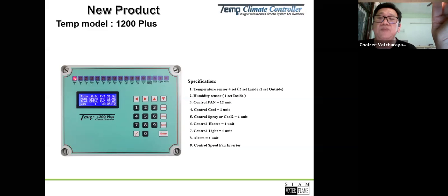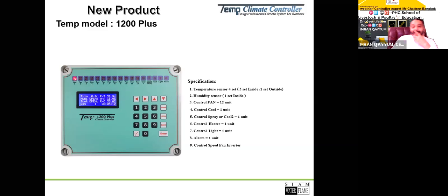For me, we prefer step, not static pressure, because the static pressure sensor's lifetime is 2 or 3 years, and it is a cost you must pay. Most customers in China also buy my controller, and China also controls the air inlet. They also use step control. Step, yes, better.